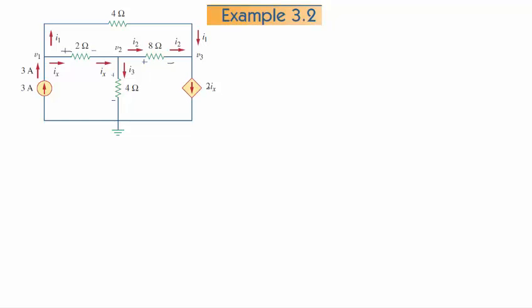And then we have a dependent current source. So the current of this branch depends on the current that's in this branch. So we'll have to account for that. So now, okay, so I have a node here, a node here, a node here, and I have a node here, voltage at 0, which I decided is my 0 reference point, so there it is at 0. Okay, now we go and write the node equations.